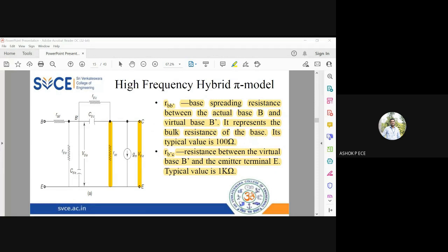See, these things you should be taught in basic electrical engineering. What happens when you are short circuiting? What happens if you are open circuiting? Voltage drop will be zero, sir. Voltage drop across the resistor will become zero. No, will this resistance exist? What is RCE parallel to 0? Well, it's the same as not having a resistance. Yes, so I can remove this RCE, right? So if I consider a short circuited load, this RCE can be removed.